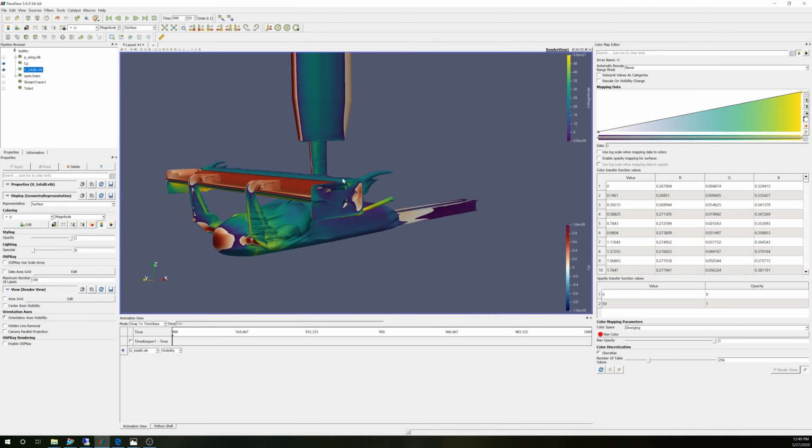So the reason you want the vents is because, as I was saying, the bottom part of the wing is what's making the majority of the downforce. The top side isn't really making that much downforce in comparison because high pressure is not the driving factor, it's the low pressure. So relieving a little bit of that top pressure isn't a big deal. You do lose a little bit of downforce, but what you gain in that little bit of loss in downforce is an overall improved efficiency because you're decreasing drag.